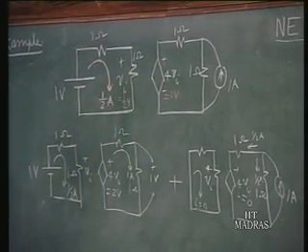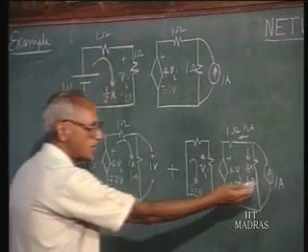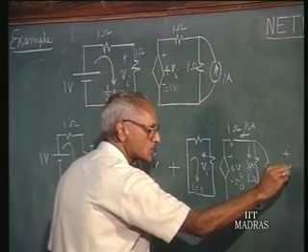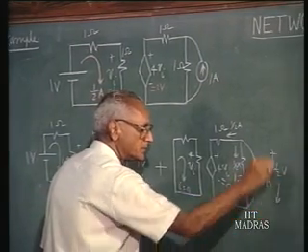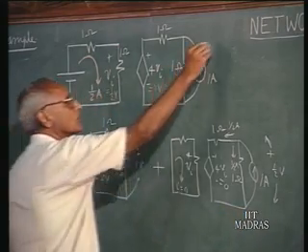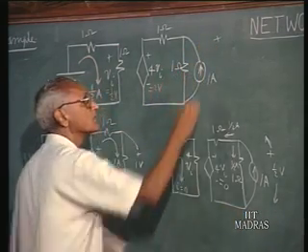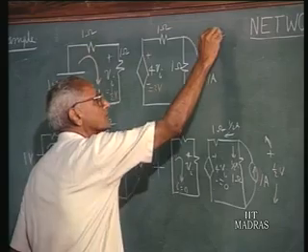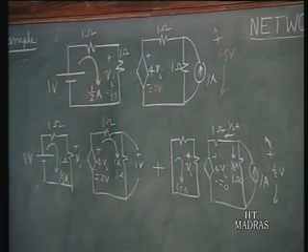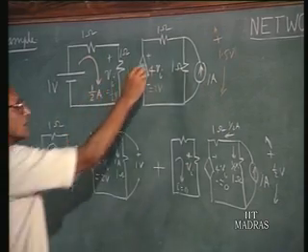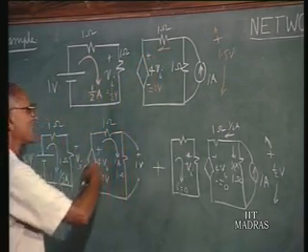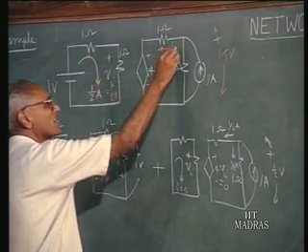The current source drives a current of half ampere here, half ampere, therefore the voltage across the current source is half volt here. This is half volt, this is 1 volt, so the voltage across the source here is 1.5 volts. And the current here, this is 1 ampere in this direction, half an ampere in the other direction, therefore this is 0.5 ampere, half ampere here.